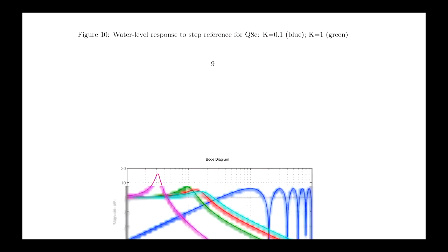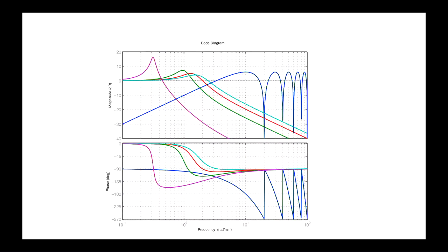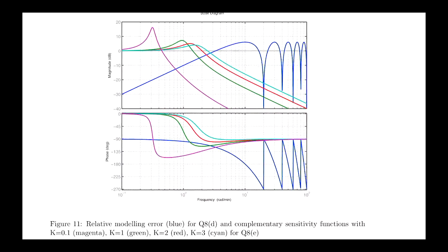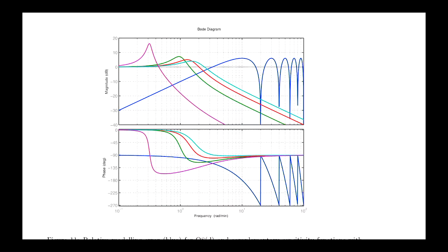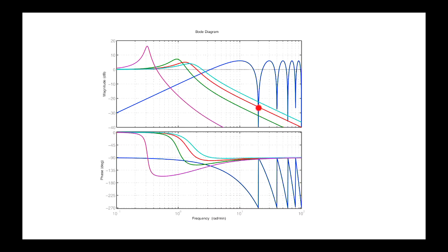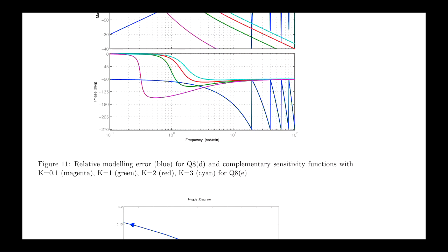In order to satisfy the small gain condition. Right. So if we look at the multiplicative modelling error associated with neglecting the delay in the open loop transfer function, you get the multiplicative modelling error looking like this in magnitude and this in phase. This phase is saying that phase is always modulo 2 pi, right? So we know that the phase of a delay keeps on becoming more and more negative, right? And I'm just wrapping that around, right? That's really just the phase becoming more and more and more negative.